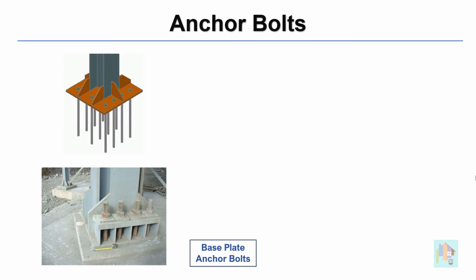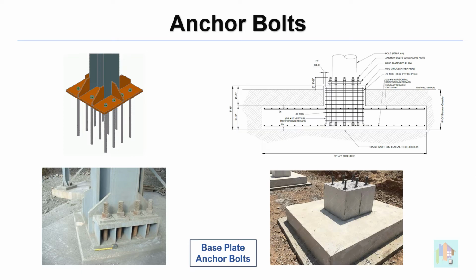This base plate is connected to the foundation or pedestal using anchor bolts. In general, steel columns are not extended below the ground. Rather, a pedestal is provided from the foundation till the column base, and all the required anchor bolts are tied with the pedestal reinforcement before casting. Anchor bolts play a vital role for the force transfer, which we'll cover during base plate design. In short, number and arrangement of the anchor bolt depend on the force or connection type.